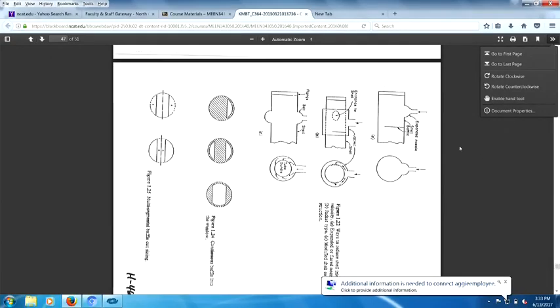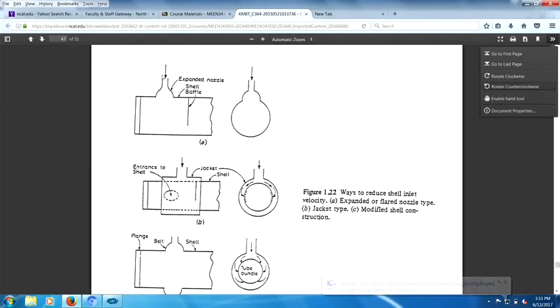Let's do a rotation here. Which way do I want to rotate? I want counterclockwise. See, this shell comes in, this nozzle comes into the shell. There's a bunch of tubes down here. You have high velocity flow hitting the tubes. This is not good. So you do an expansion nozzle on it. This possibly will lower the flow. I don't think it'll lower it that much because the momentum of the jet will continue, and it smacks up against those tubes. Okay, only part of the tubes. The rest of the tubes are not slammed that easily.